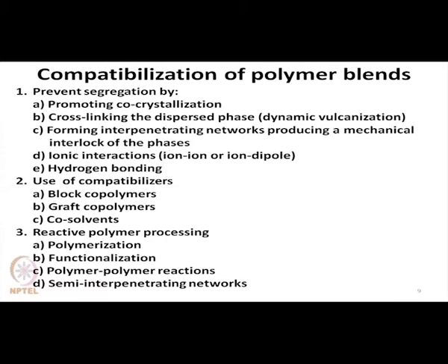Then after filling the mold, the polymer-filled mold is cooled at a specified rate of cooling. Now, that specified rate of cooling affects the molecular alignment, or organizes these molecules to have long range order in the product.